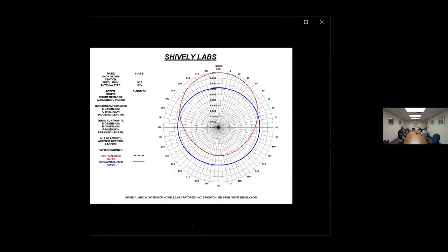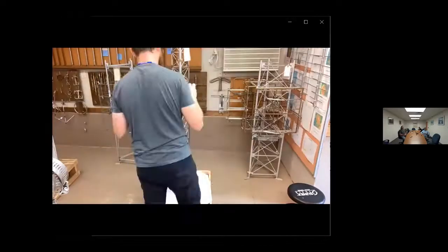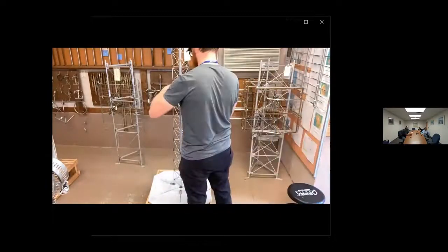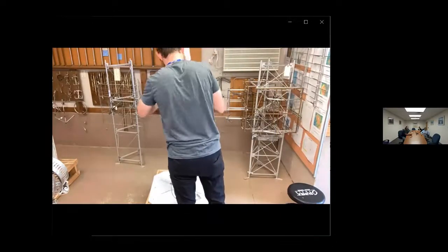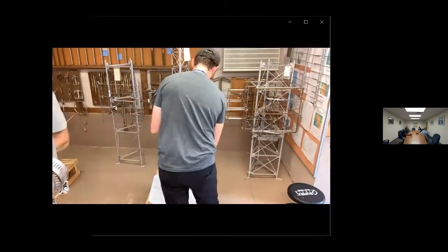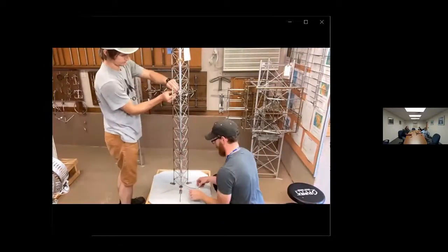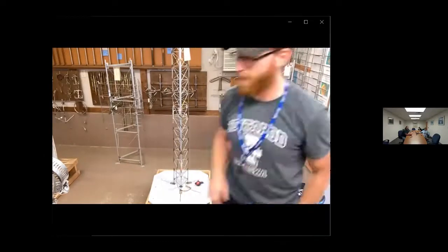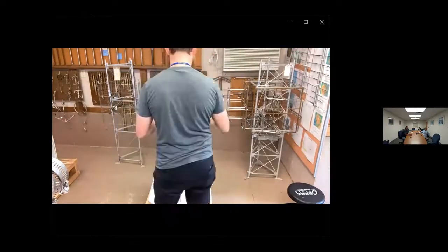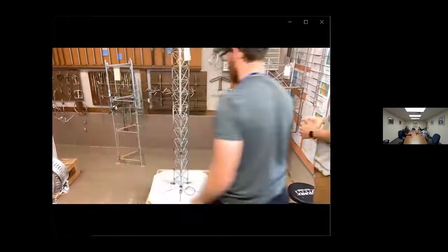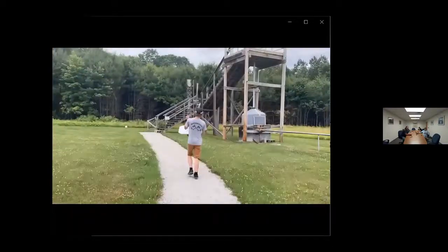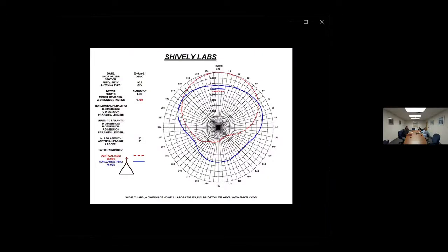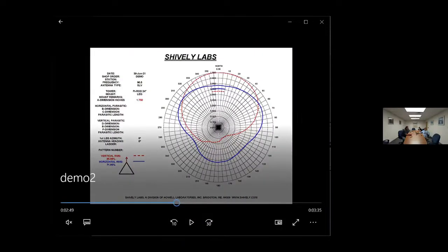After we've determined that the model and range are trustworthy, we proceed to mount the antenna to our tower. It is for sure going to be placed on the aforementioned vertical offset pole, but we could choose whether that pole gets mounted on a leg or a tower face. That choice hinges on the tower real estate, orientation, and customer preference. After those, if I still have that option, it comes down to whatever's best for the pattern.